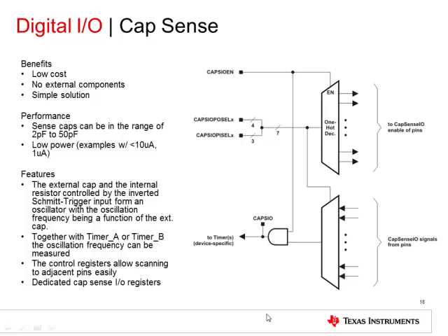The Capacitive Touch IO module allows implementation of a single capacitive touch sense application. The module uses the integrated pull-up and pull-down resistors and an external capacitor to form an oscillator by feeding back the inverted input voltage sensed by the input Schmitt triggers to the pull-up and pull-down control.